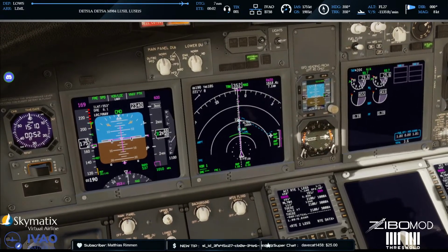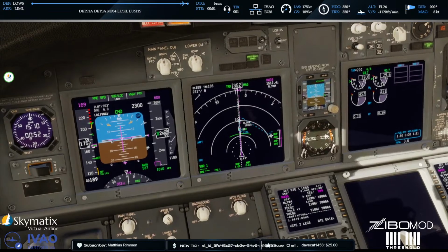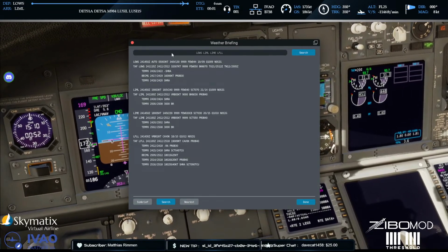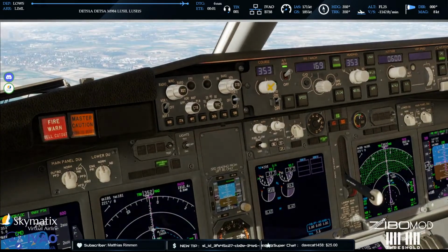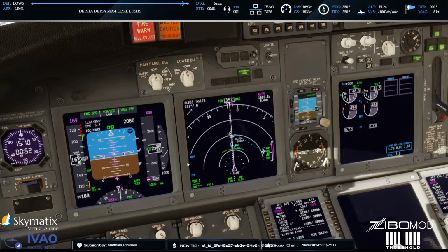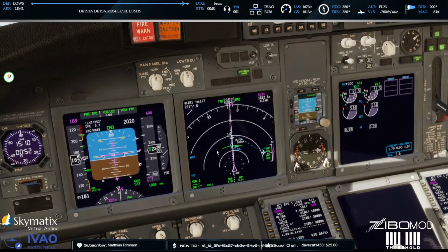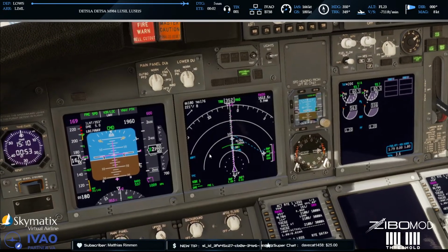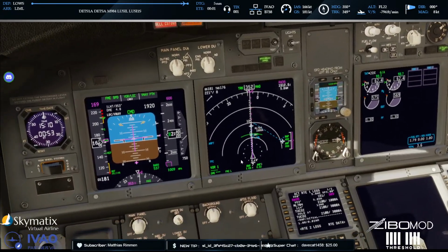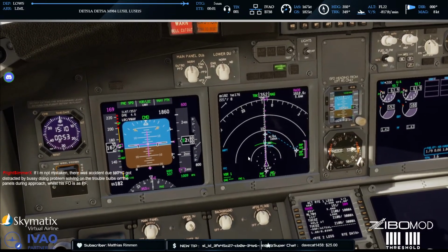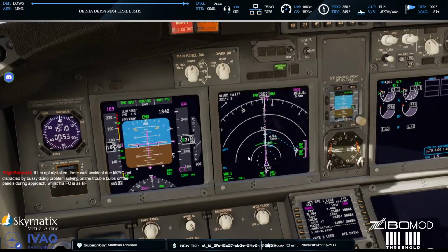Is the QNH correct? 6 nautical miles times 3, you should be at 1,000. It changed, 1019. 1009 or 1019? No, it's 1009. So 5 miles on a 3 degree glide, you should be at around 1,500 AGL.